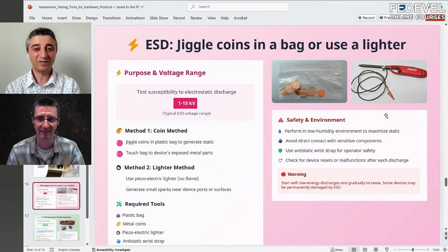Basically, ESD, the electrostatic discharge, is one of those little tiny things that you might think, why would it fail? But it might sometimes kill a chip if the amplitude or the voltage range is so high. And you can buy an ESD gun that can do a proper ESD test as per the IEC standards. There are levels like 4 kilovolts, 8 kilovolts, 15 kilovolts, a number of pulses, how you direct them, and the polarity. Exactly, the air discharge and the contact discharge test.